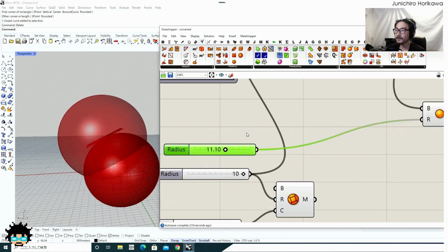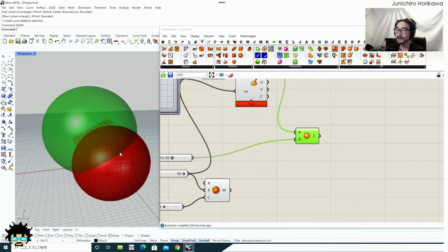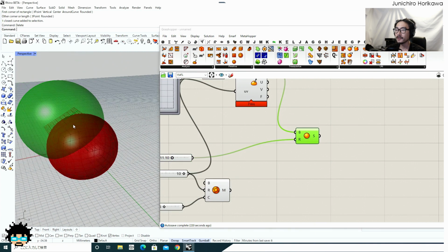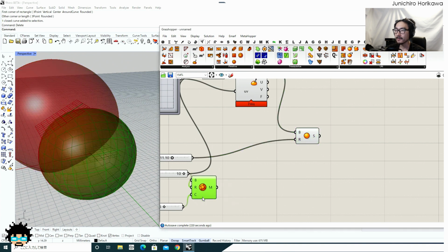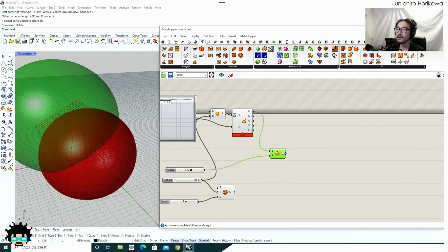Like this. And I'm going to use this sphere as a power field to push the points inside this sphere. In this case, the points are the vertices of this mesh. I would like to move the vertices which belong to this mesh, inside this sphere, in an inward direction. Alright, and let's also define which direction I want to move the points.